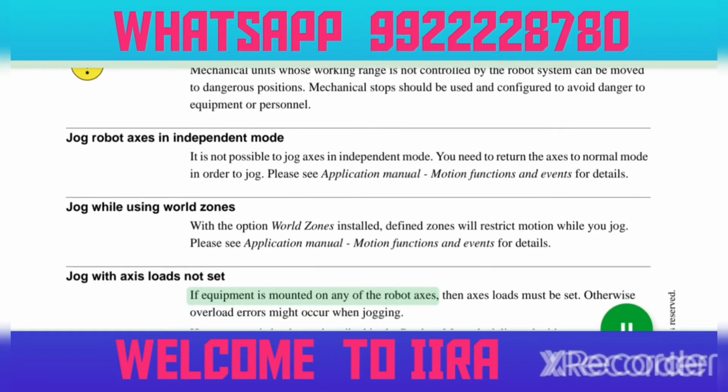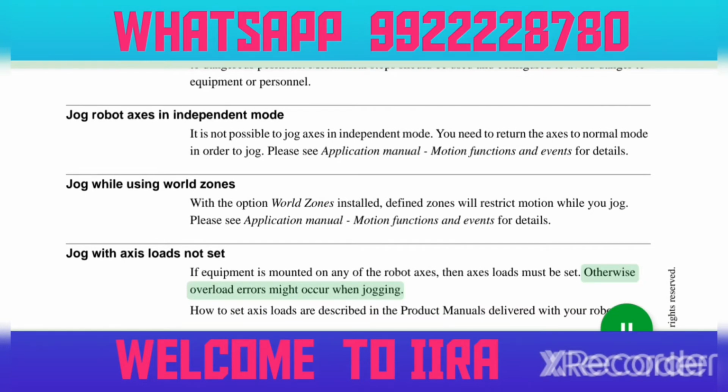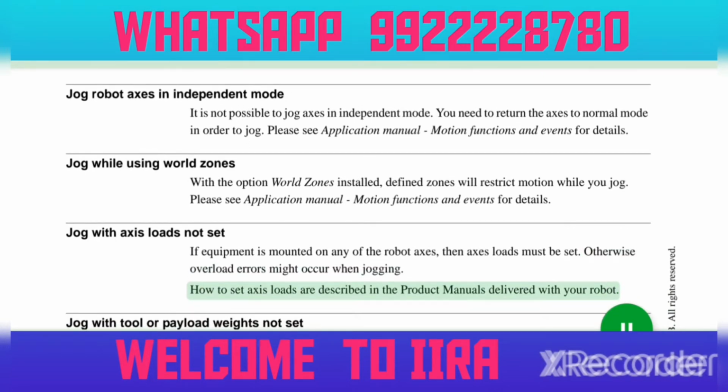Jog with axis loads not set. If equipment is mounted on any of the robot axes, then axis loads must be set. Otherwise, overload errors might occur when jogging. How to set axis loads are described in the product manuals delivered with your robot.